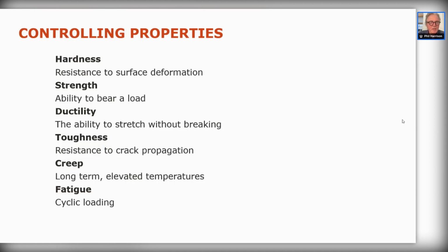A brittle material has zero resistance to crack propagation. When you have a brittle material, once it starts cracking, in the majority of cases the crack will continue through to destruction of the test piece or material without any additional loading. Whereas if you have a material that's tough, you have to keep putting load into the material to cause failure.